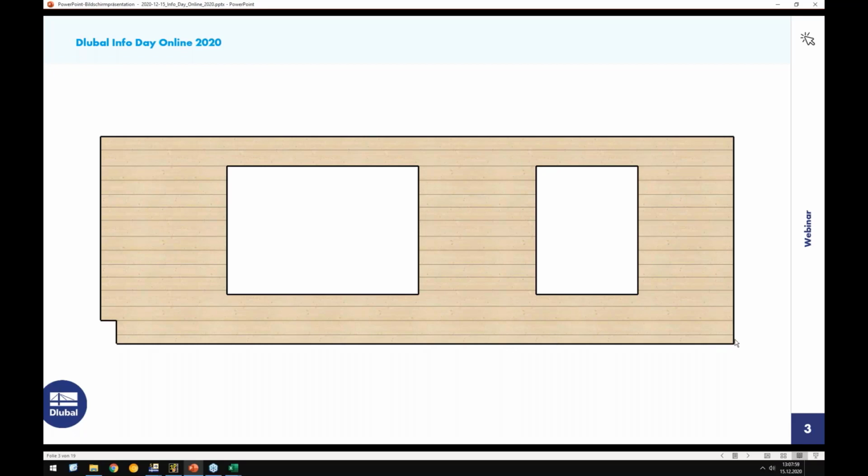That's one important thing, that we need to take care of the orthotropic direction. So the outer layers should be horizontal, and every second intermediate layer should be orientated vertical. Okay, so the next thing is, of course, we need to take care about the supports. In this case, it's just, for demonstration reasons, a nodal support. We will not use it afterwards in our design, but for the slide, it is okay.